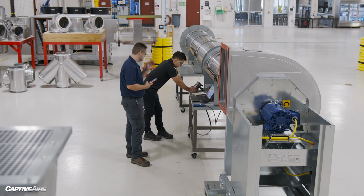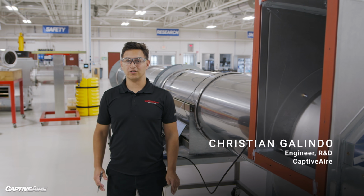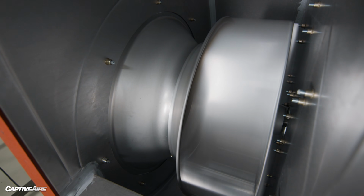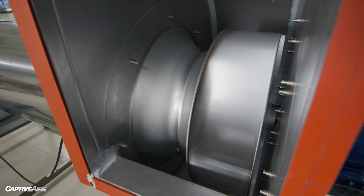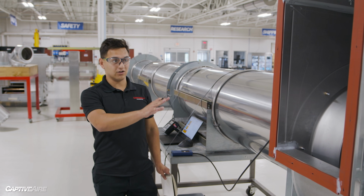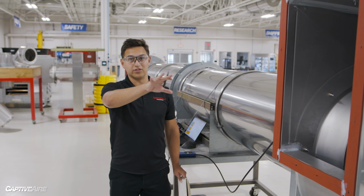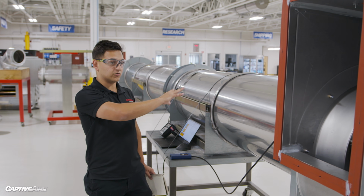Today, we're out in the lab at R&D. I'm going to develop our master RPM curve for our USB i24. Typically, we send all of our fans for AMCA testing, in which they develop the curve for us. When they test our fans, they do it with no accessories on top of our fans. It's just the fan itself. So as you'll see here, we have no discharge cover, no dampers, no discharge extension anywhere on this unit. We're just testing the fan itself, and we'll go over all of the parts of our test rig next.